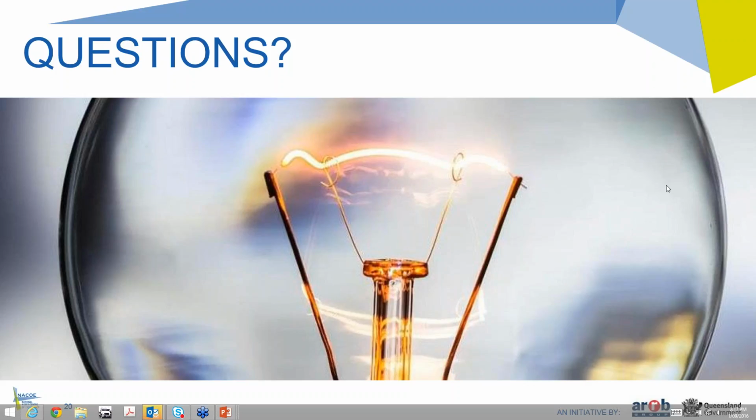So all those things we addressed. We also revisited the presumptive design moduli that we were using, and based on more recent mixes we're able to increase the moduli, which resulted directly in a reduction in thickness. So it wasn't really one individual thing, it was a whole lot of little things that really added up to the difference that you can see from that chart between the 2009 and 2013 thicknesses.